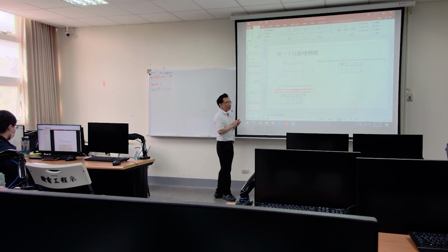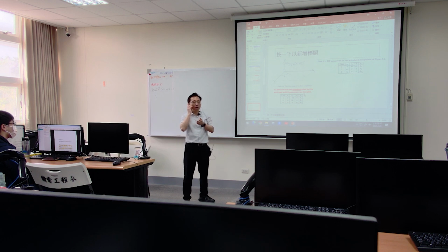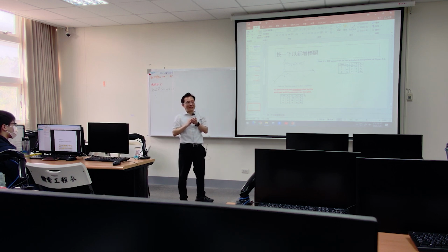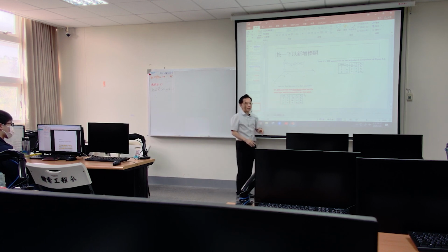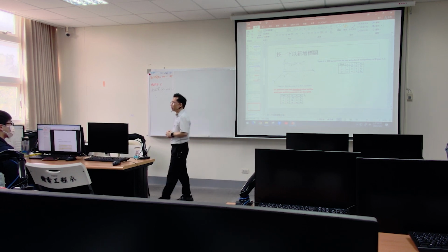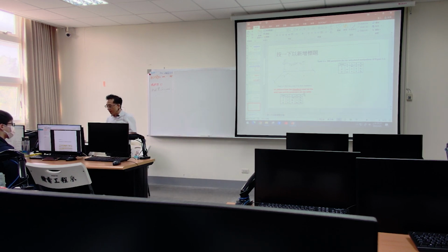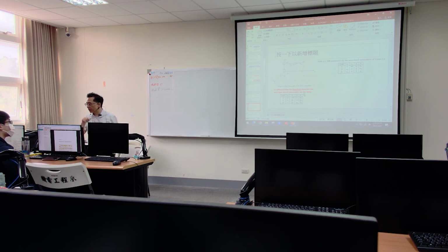But for the Stanford, you don't need to memorize that, I just want to show you. The first 3 joints are a little bit different. They have a prismatic joint for that, but the last 3 are all revolute, so it's the same type. No, not the same value, the same type. Okay, so they don't have a, because a is the offset, I think. And for the first one, it's different. For the first 3, joints 1 to 3 are different compared to the RRR. I think that's what they try to say, okay?